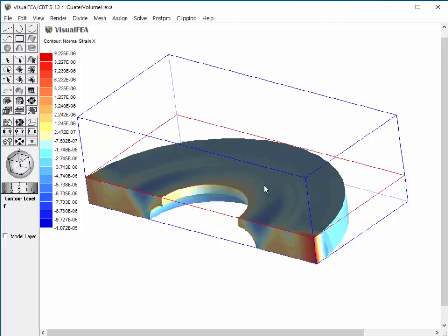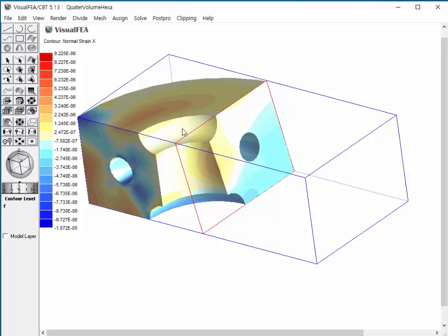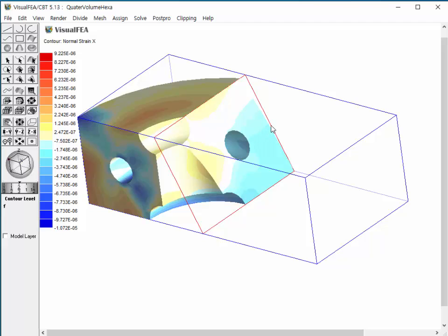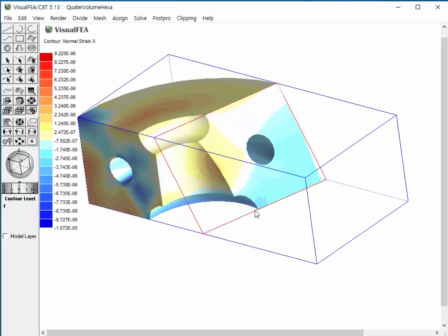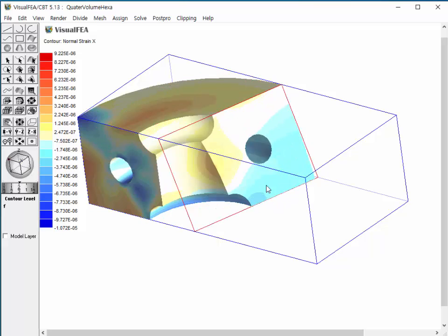The clipping plane can also be made inclined in arbitrary direction. Instead of dragging the plane, with the cursor inside the plane, click an edge of the plane, and drag. Then, the edge of the clipping plane moves, and the plane becomes inclined following the edge movement.